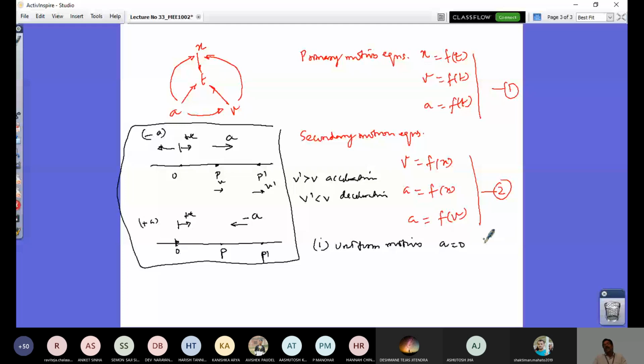So you may ask, that is a statics problem. Why do we have to say? Because it's important when you go into curvilinear motion, you can have velocity 0, but still acceleration exists. So this is a case where acceleration is 0, but velocity exists. So just to have that understanding, we call this motion uniform motion, where acceleration is 0. You can have your x represented as a function of t, and from this v equals dx by dt. This is how you define a motion parameter, velocity.